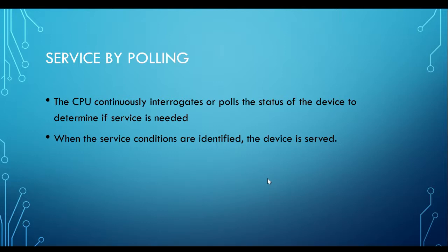Okay. In every main line, maybe your main program consists of 4 or 5 lines, and one of the lines will consist of checking if flag equals to 1. Okay. You do this. You blink an LED or do whatever. You have a poll. Okay. Now this is a polling system. You can integrate this polling system with functions, okay, subroutines, function or whatever.